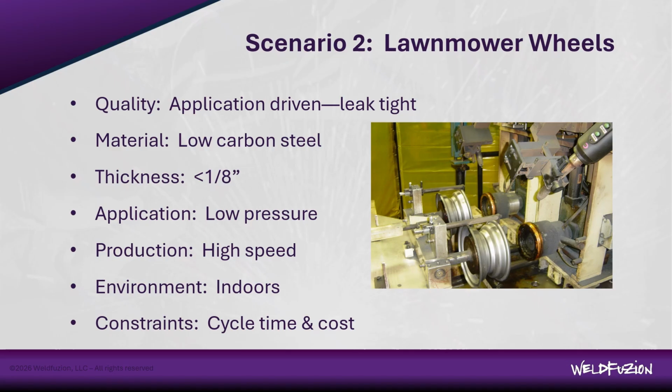control process. At the same time, in this case, the wheels were all the same size and shape. And let's face it, they're welding millions of them. Handheld welding just wouldn't be capable of hitting the required speeds at the necessary quality, right? There's just too much deviation there, too much going on, too fast. You need too many operators. So they completely automated this process, and then one welder could kick out thousands of rims per shift. So that's a way to look at how manufacturing may be different from fabrication and or repair.